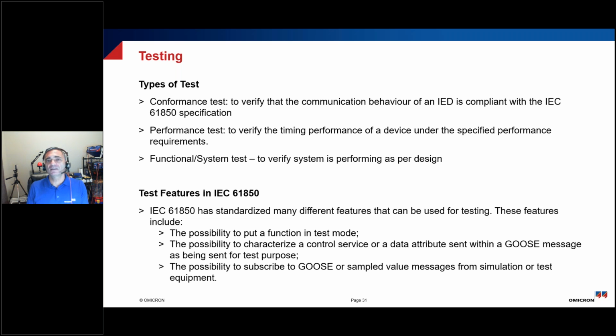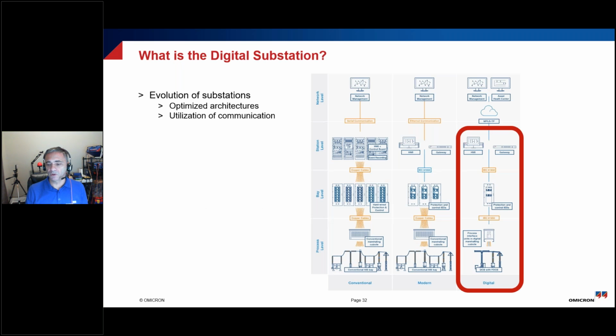So the idea is to try and test these devices without removing them, and that's the ultimate goal, because it reduces labor, and it's safer to do it when you're not actually having to remove and install the devices themselves. And so there are new features called the test feature mode and the simulation mode that allow you to test these devices without taking them out of the substation. And this is very unique to this protocol.